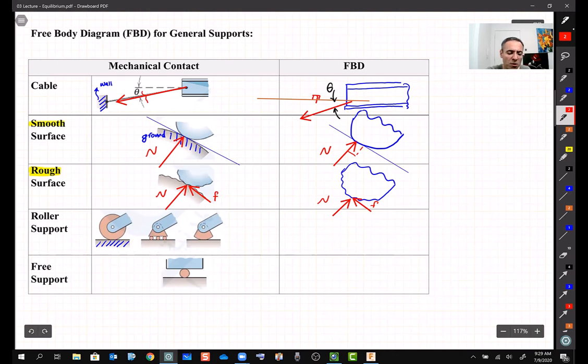The role of this roller is basically to let you move it freely left and right, right? You can move it up, but this roller doesn't let you press it down, basically, right? Move it down. So in fact, the reaction that this roller applies here is just one vertical reaction load